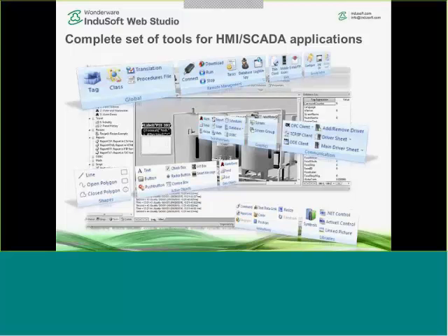As I mentioned, we install over 200 native communication drivers along with the product. So for the vast majority of PLCs that you may need to interact with, or equipment that you may need to acquire data from, we give you a way of communicating natively with those devices without requiring any third-party communication software. But we do also support OPC, and the reason for that is we don't have every protocol. If we don't have a protocol, we give you a full library of different OPC DA, UA, OPC .NET. So it really opens the world to getting data into the product from just about anything.